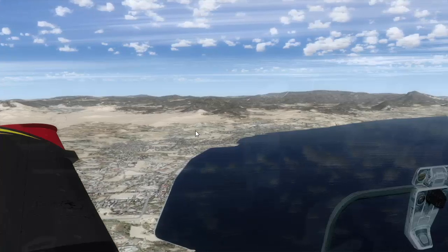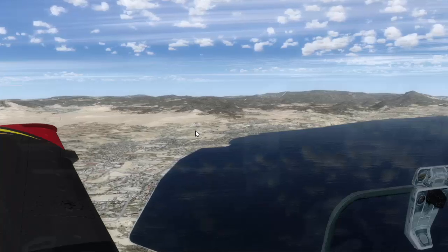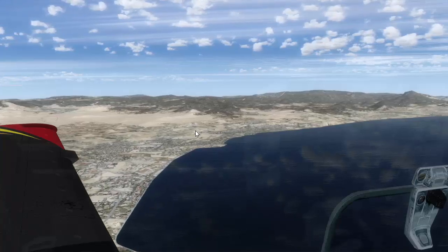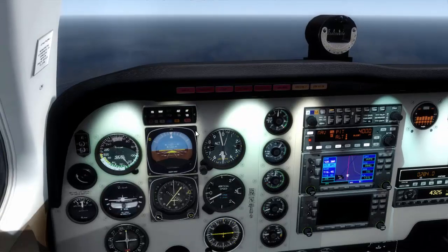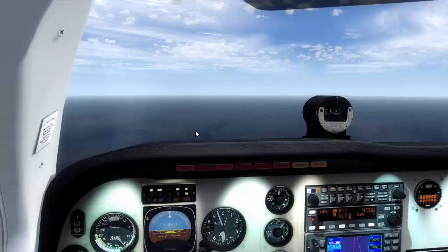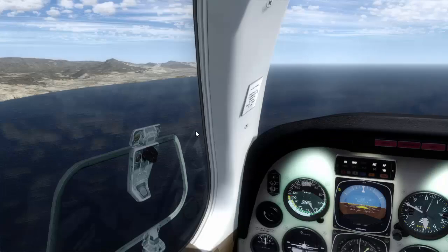because I remind you that this is not a precision approach. If you want a total precision approach, you need to use the ILS, the instrument landing system, because the ILS is the only precision approach with which you can land your aircraft almost automatically. But when you are proceeding with a VOR DME approach, you are getting a non-precision approach, okay,